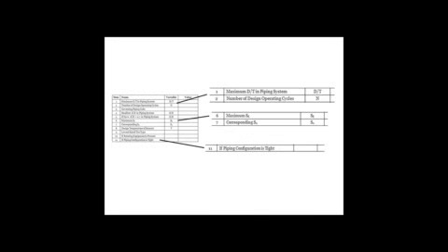So let's identify the most critical criteria. And excuse me for repeating myself, but this is the most important criteria. Number 1 is D over T. Number 2 is number of cycles. Number 3, is the piping system tight? You've got to be able to make that determination. And then, are there areas of the pipework that show to have relatively high stress? Because these are going to be the worst case.